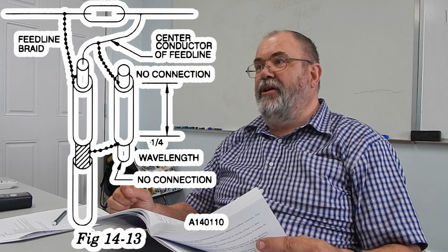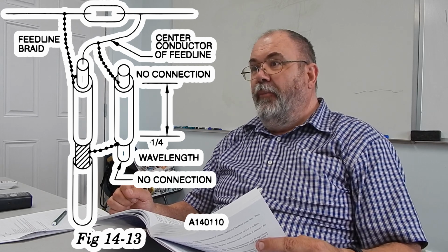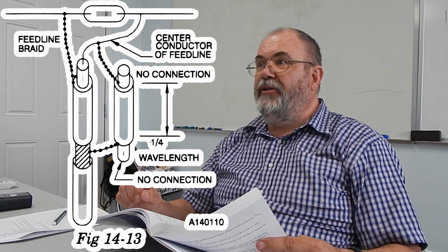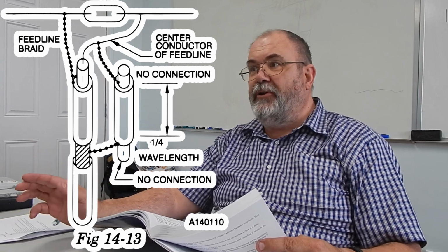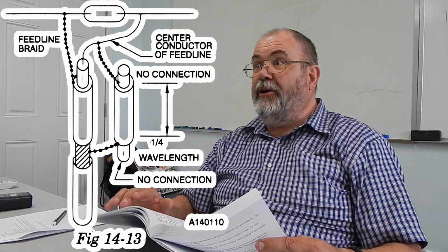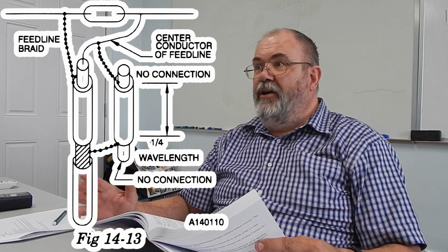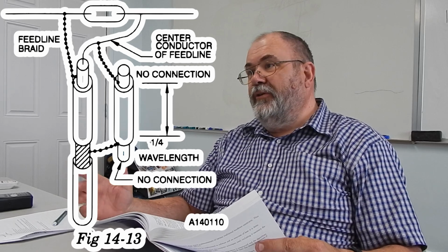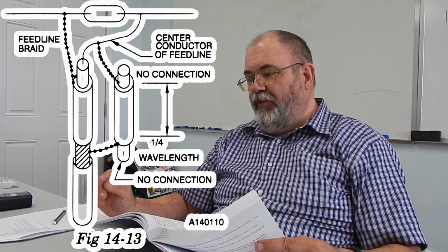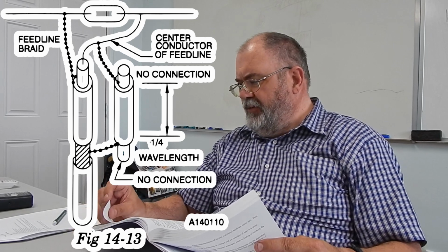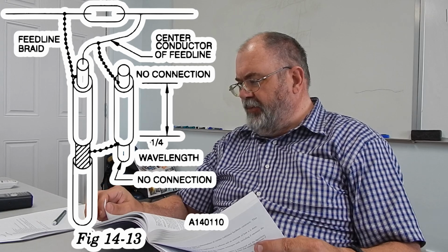Yeah, pain in the butt. But if all you did was 20 meter CW contesting on a little sliver of the 20 meter band, you can very easily make an antenna that way, and as long as you don't tune outside that range of the band, it'll work fine for you. So everything's a compromise. It's a simple thing to make, but it's a compromise. It's a very compromisey thing.